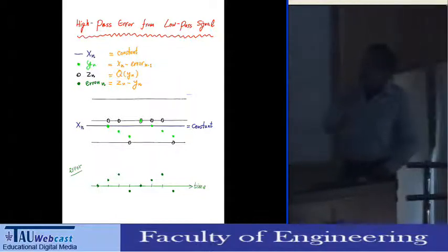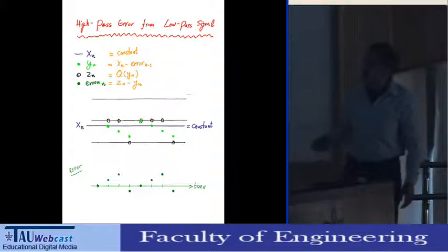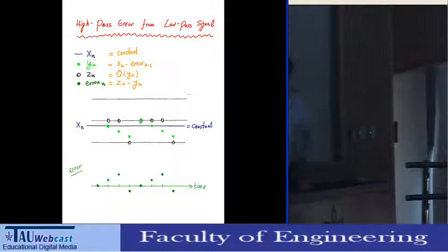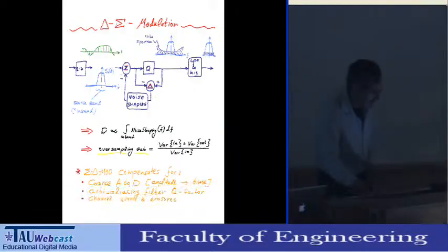And here I'm just showing that even if quantization noise is not additive, you can put in a DC signal and calculate what happens in this recursion, and you will see that the error signal is like high-pass, although the signal is not changing. So this phenomenon is also true for deterministic quantization.